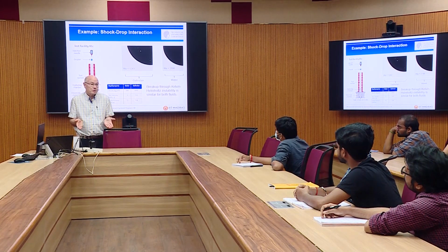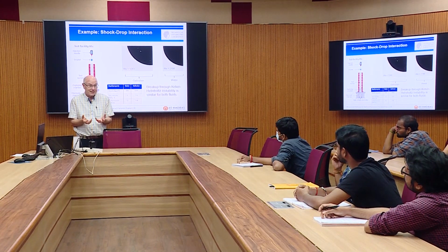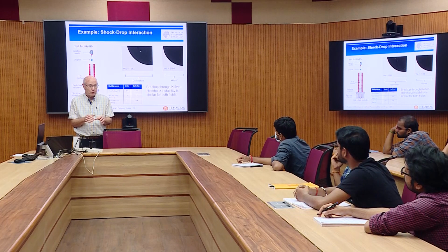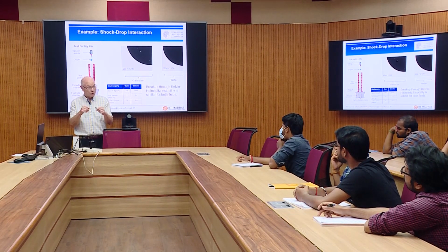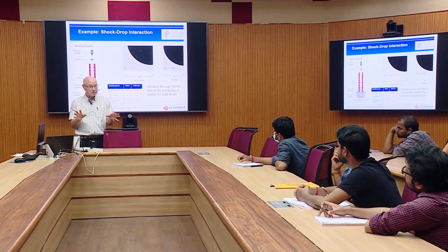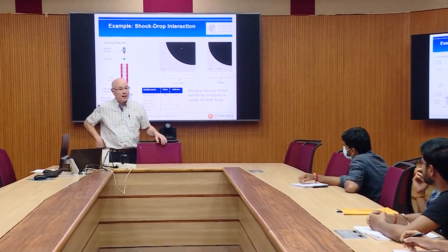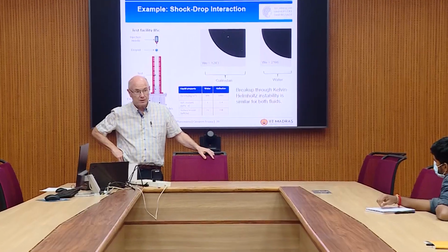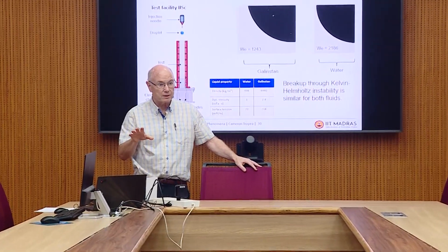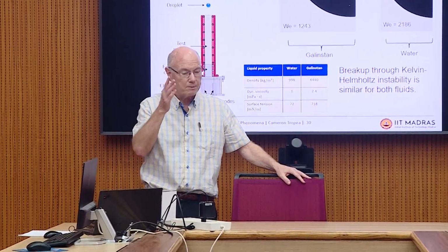Of course, one thing is you have to make sure that the liquid is very clean so that there's no clogging in the hole. The other thing is the way these holes are manufactured is very important. They do get a sort of rounding at the beginning. And otherwise, you have to keep your frequencies very monotone. Not monotonic, monotone.